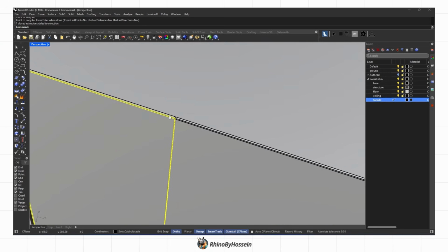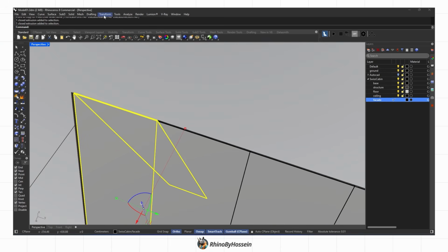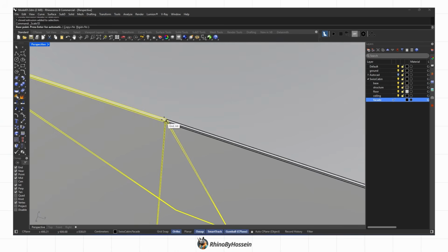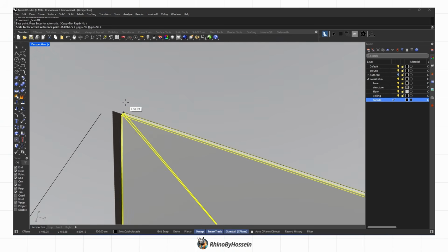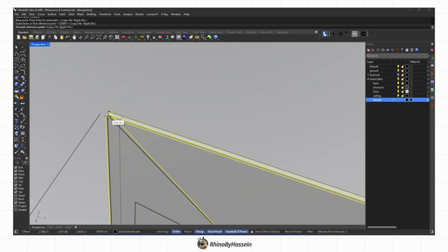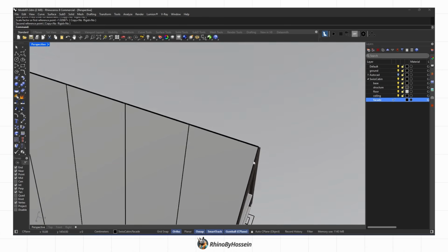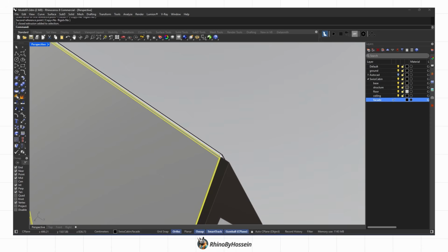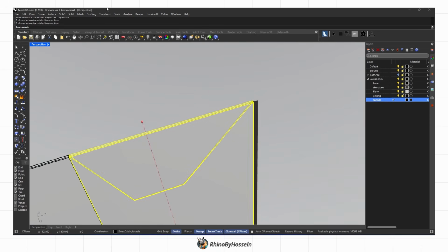If the sheets are slightly larger or smaller than the beam spans, we use the Scale 1D command to fit them perfectly so the sheet dimensions align properly with the structure. This ensures no discrepancies in sizes and that all parts fit together perfectly.